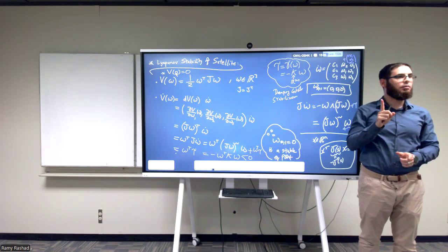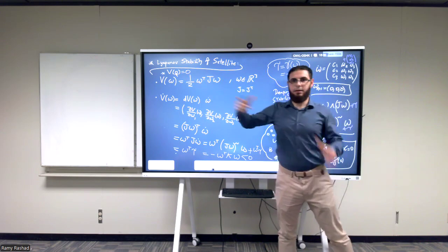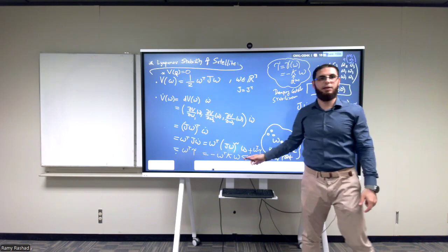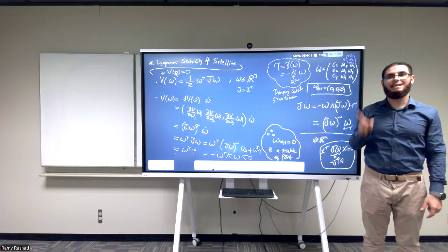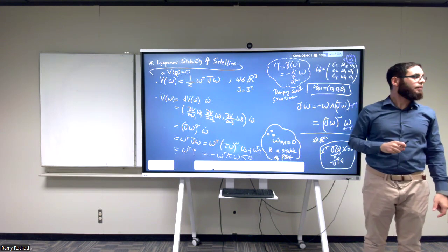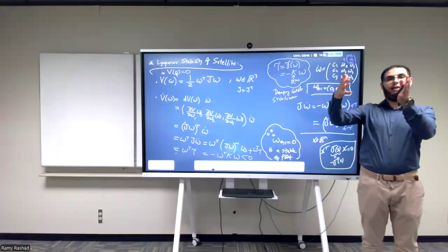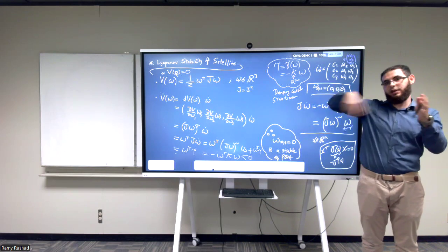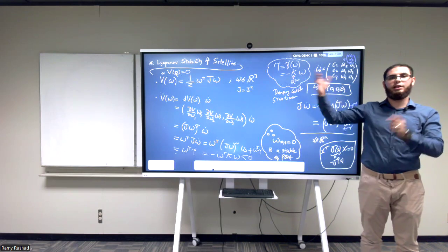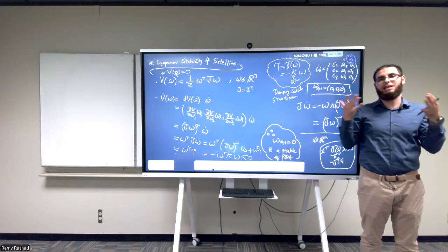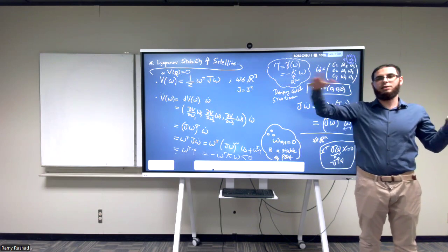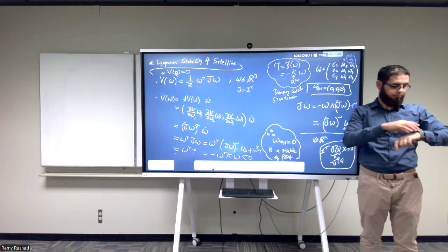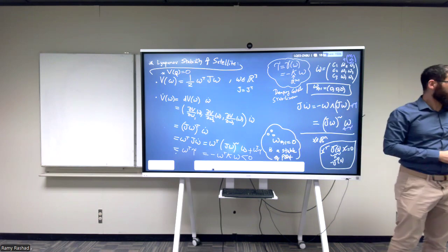Not only that, this is a quadratic function that is radially unbounded, and I have this to be negative definite. What is the result that we have here? It is globally asymptotically stable, which means that this system, this satellite, starting from any initial condition, if something very hard comes and hits it and makes it rotate very fast, this simple controller will make sure that it stops eventually. Of course, asymptotically. What does asymptotically mean? It means as time goes to infinity. It means very slowly it will start to come back and stop. So it is globally asymptotically stable.